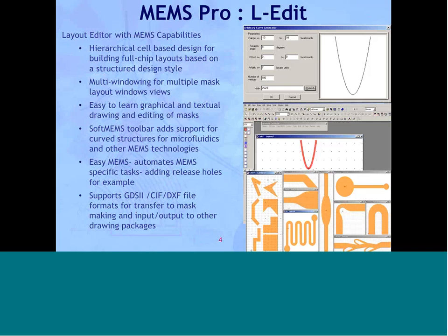So if we look first at the MEMS Pro LEdit package, as I mentioned, it's a layout editor with MEMS capability. So in other words, you're using a popular IC layout editor, but we've added a lot of MEMS-specific features because MEMS has very specific requirements in order to create MEMS structures that are not typically found in IC design tools. But we wanted to choose a layout editor that already exists, and we didn't want to reinvent the wheel. So we chose a popular layout editor, LEdit, and added a lot of